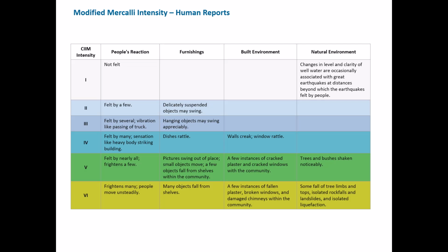And liquefaction, we'll talk more about liquefaction later on, but if the ground has some high moisture content or a water table underground, then what happens is that the ground's a bit porous, and under the shaking, there's this like capillary effect, and the water gets drawn up, and that reduces the strength of the soil. It becomes more weakened. And we'll look at some slides later where in Japan a number of years ago there was an earthquake that caused this liquefaction, and some apartment buildings just toppled over. We'll see that later on.